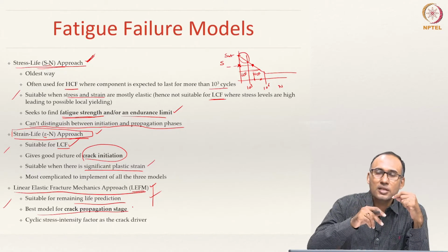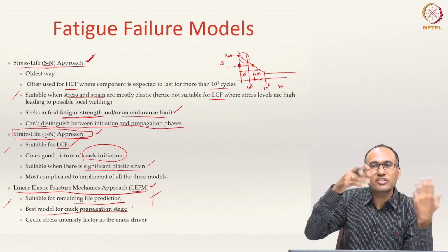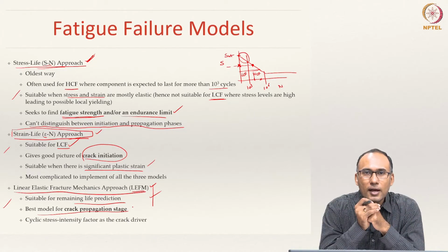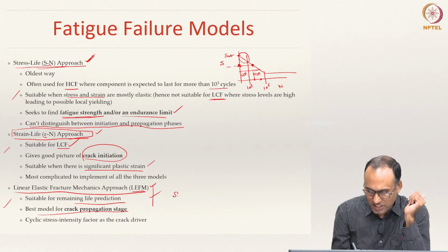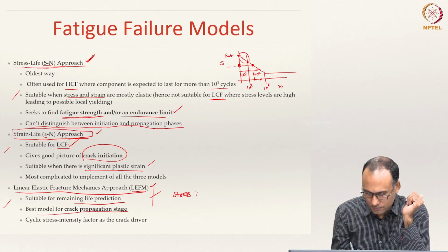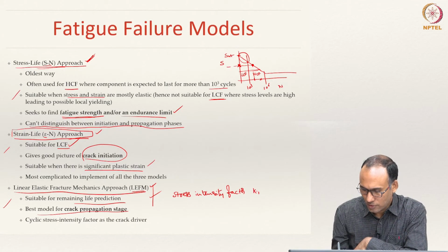And you know that the stress state is changing as a function of time, that means the stress is cycling between two values. When we talked about linear elastic fracture mechanics in the previous module, we introduced a very important concept called the stress intensity factor, K1.